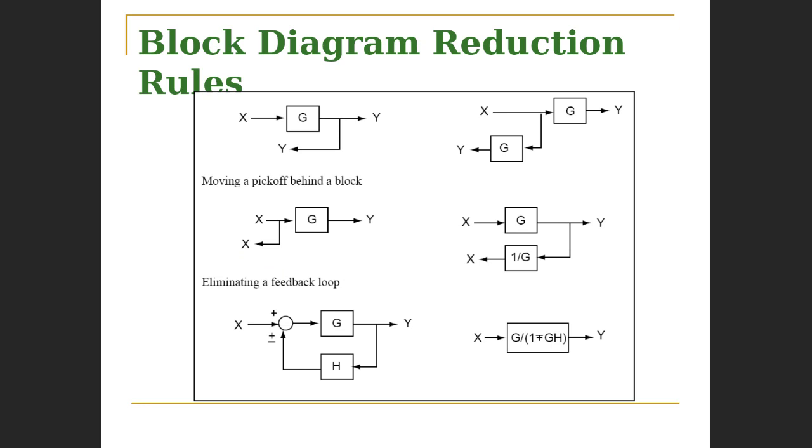So what I'm trying to do here is to provide you with a means of remembering the rules. This is something that you perhaps have to do on your own time, but I'm just giving you a kickstart on that. You need to know the rules. So here I'm showing you, as I've done in the previous cases, what we're seeking to do here is to move this pickoff point called X to the output. Now, if we were just to move the pickoff point, what signal are we actually getting? We're getting Y. Go ahead, Richard.